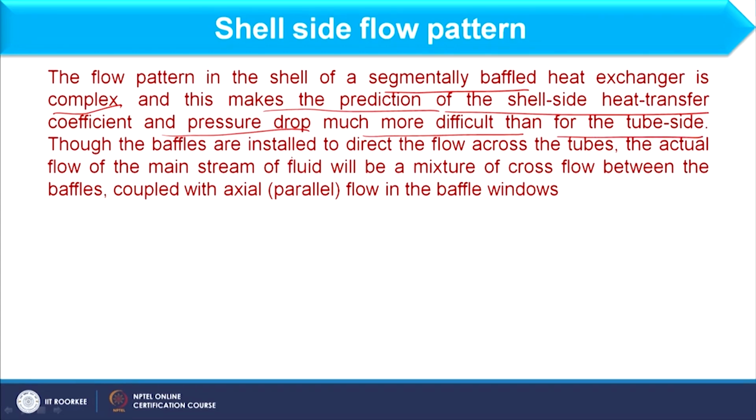Though the baffles are installed to direct the flow across the tube, the actual flow of the main stream of the fluid will be a mixture of cross flow between baffle tips coupled with axial flow in the baffle window.